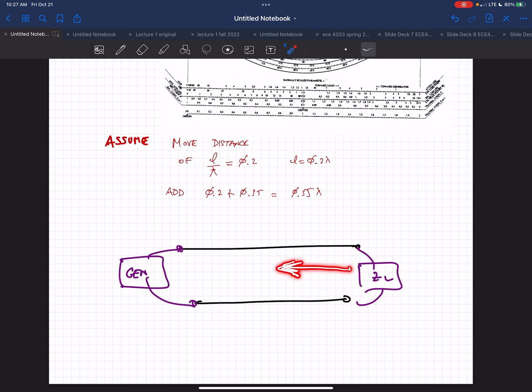So it's starting from the load, going away. When you're going away from the load, you're going towards the generator. And so the distance is given in wavelengths towards the generator. And if we'd gone the other way, towards the load, it would be wavelength towards the load. Does that make sense? So when we reference Z to 0, we do it that way, but if we did Z to 0 at the generator, we'd do wavelength towards load. Exactly, yeah.